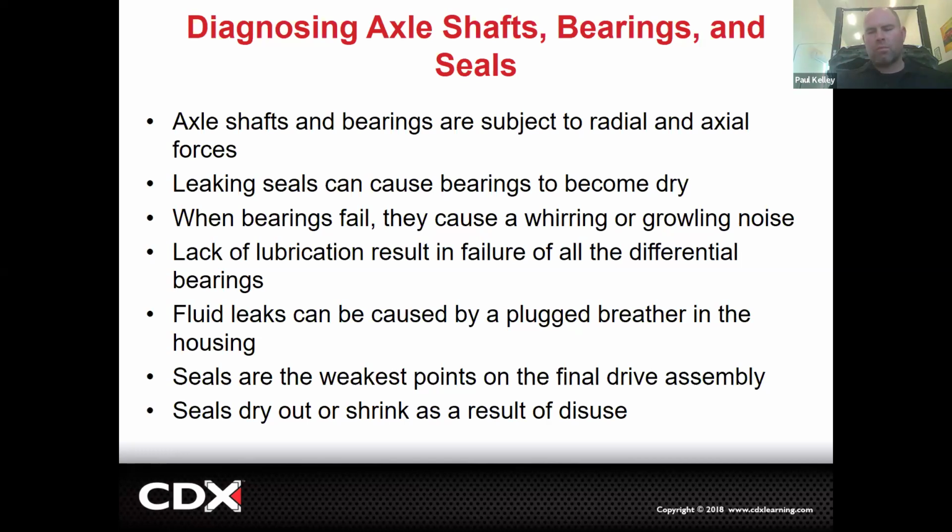Cool. And we have different ways to kind of narrow this down. So if we think it's those axle bearings out at the ends, how would we manipulate that noise? We think it's one or both of the end axle bearings. Steering the vehicle is going to change the load on that bearing because the weight's going to shift to the outside. And if you turn left and it gets louder, I'd say it's probably that right rear axle bearing. It's coming from the back.